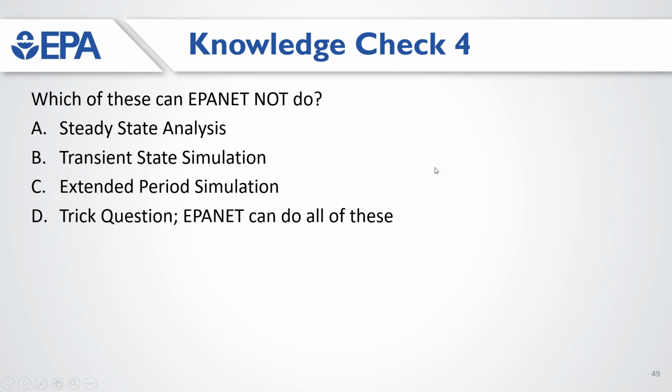Well, a little bit surprised. I think I didn't do a very good job. Yeah, EPANET cannot do transient state simulations. So it's always a steady state. Some people, especially people who care a lot about plumbing, probably got disappointed, because transient analysis or water hammer analysis is very important for many hydraulic systems.